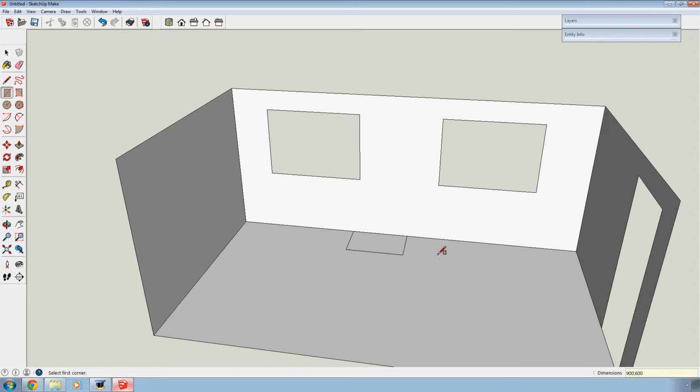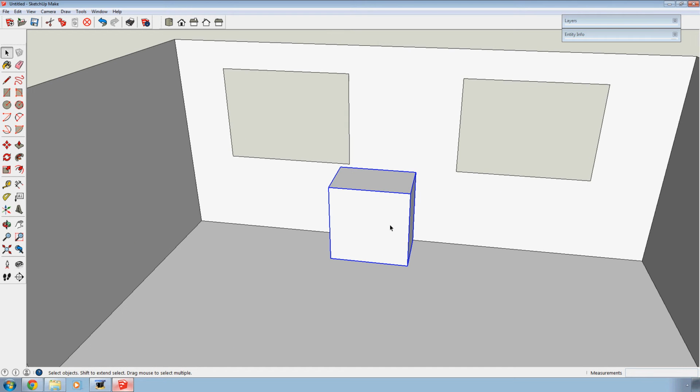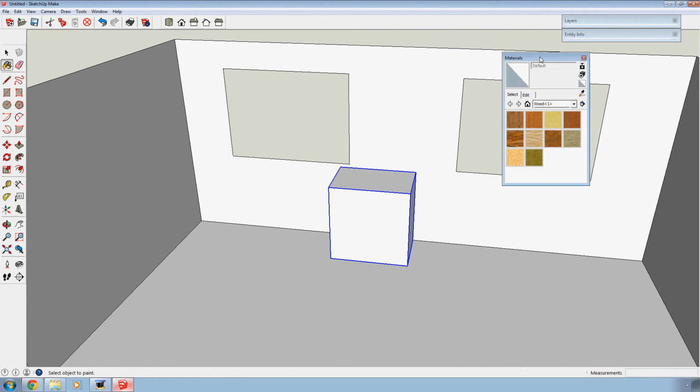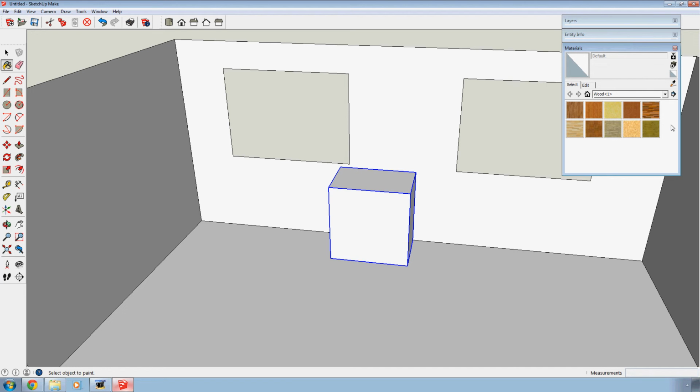and we know that the height's going to be 915, so I'm going to use the Push/Pull tool, pull it up a little bit, and then enter 915. You saw it jump up, and I'm now going to make this into a group. And just to show that it is an appliance rather than one of the cabinets, I'm not going to bother to draw rings and things on it, so I'm just going to press the B key. That will give me my paint bucket, and I think I'm going to do this one in a metallic color.